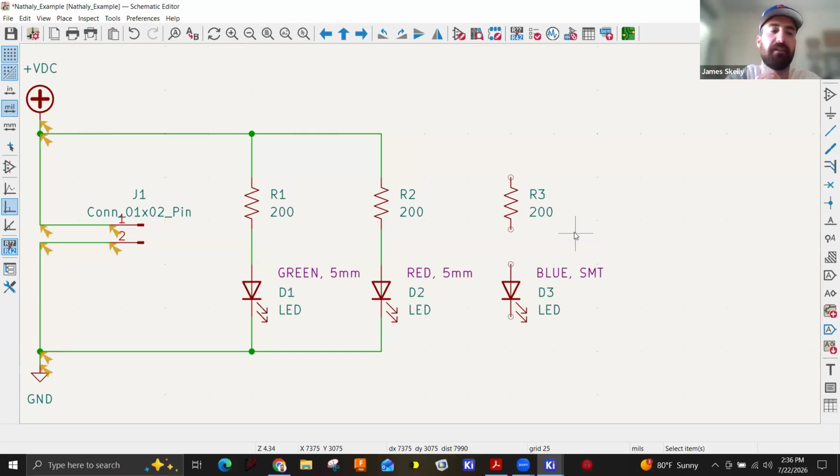And they're just telling you the size of the sides. Like 0603 means that one side is like 60 mils and the other side is 30 mils. And I should specify, mils is a very interesting unit that you've probably never heard of because I feel like only PCB people talk about it. Mils are not millimeters. They're very different. Okay. You see how this says mils and this says millimeters? Yes. A millimeter is 1/1000th of a meter, right? A mil is 1/1000th of an inch.